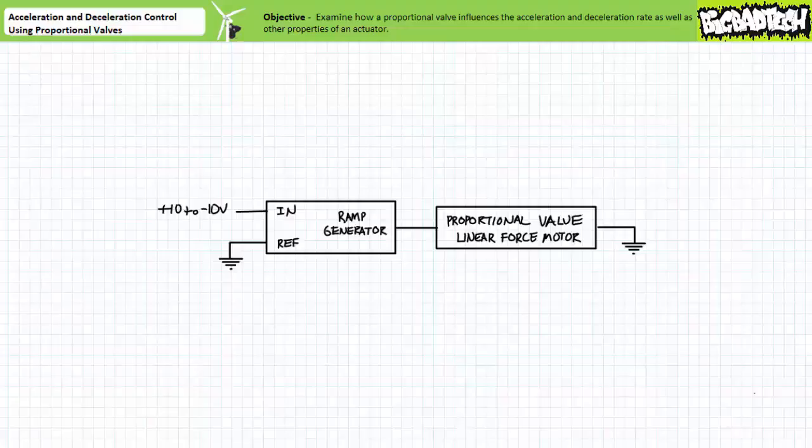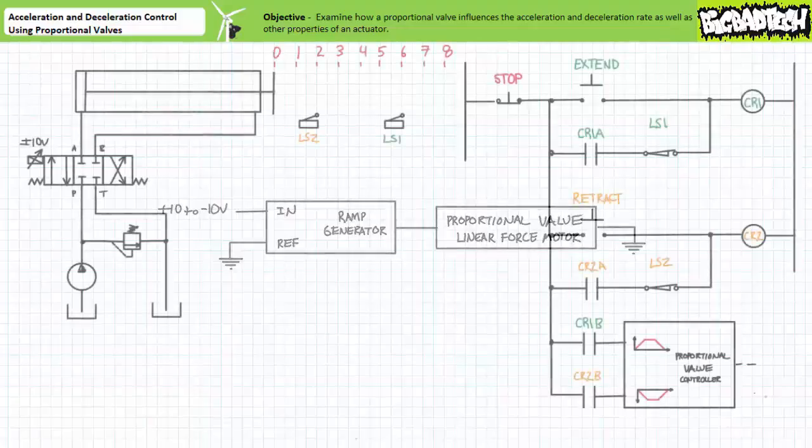This block diagram using a single ramp generator is basically tying together the enable and source for what would ordinarily be split into two separate ramp generators. Long story short, they do the same thing, however they use different means of depicting this function. I'm going to stick with two separate ramp generators for the purpose of this analysis since I find it easier and it doesn't necessitate any changes to our existing ladder logic diagram.